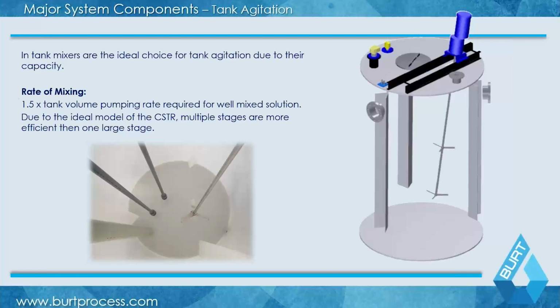It basically cuts right across the top of your system. And that's really done by looking in here. You can see an actual picture of one, by having that downpipe and then having that properly designed agitation. I'm not going to go into too much detail today on how agitators operate and the sizing of them. But as a rough calculation, as I said before, about 1.5 to 2 tank turnovers per minute is fairly common for agitation in a pH neutralization vessel.